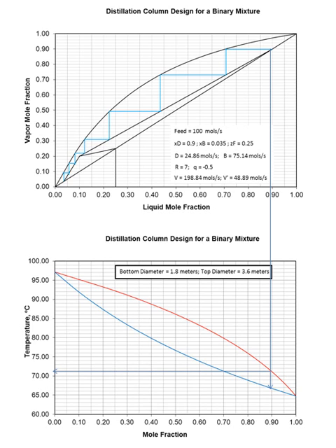In this case, for the vapor at the top of the column, where that line intersects the vapor line, we find that to be approximately 71.5 degrees Celsius. The liquid leaving the condenser is calculated to be about 67 degrees C. So now we have the temperatures in and out of the condenser. This will allow us to do an energy balance and therefore calculate the area of the condenser.